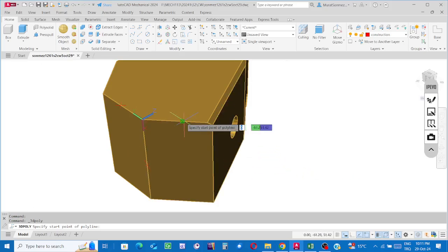For nodes, AutoCAD uses a green little circle with a green tilted cross. This is the first point I can indicate. This is the second point I can indicate, but the third point cannot be indicated. Unfortunately, be aware, the third point cannot be indicated.